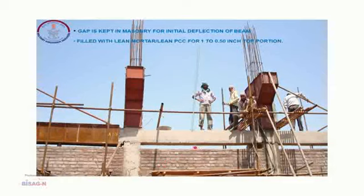We can leave a gap below the beam so that it can be filled afterwards. If we do not leave this gap and we fill up to the beam bottom and we load the beam at later stages, then it deflects and transfers the loads to the wall, which is a partition wall and not supposed to take the load. So, cracks appear, and for 2-3 years, unless it is stabilized, cracks can be seen.